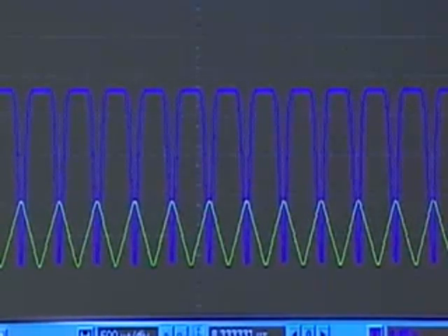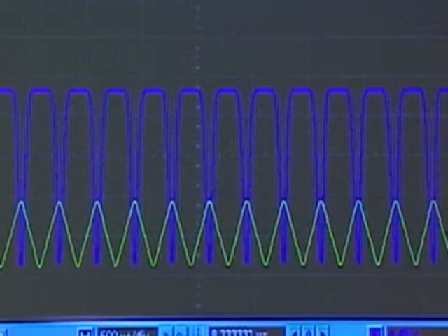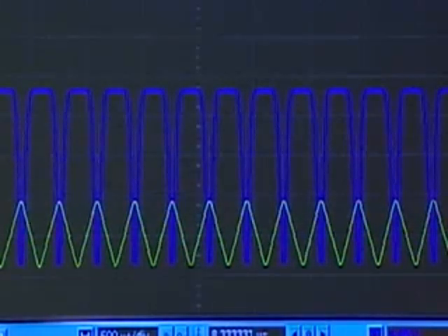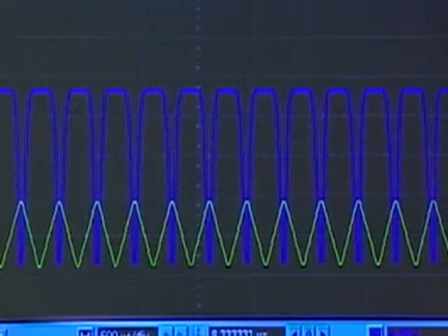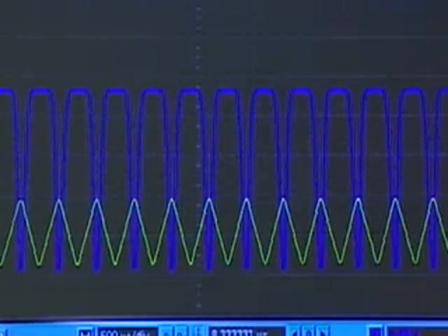Okay. So the triangular wave is my input, and this is my output. This looks nothing like a triangular wave, and the reason is that I don't have the right offset. Okay? So what I'll do is gradually increase the offset on the MOSFET. So at this point, the offset is very low. Okay, I have a very small, near zero offset, and so therefore, my output's a disaster. My MOSFET is not in saturation all the time. So what I'll do here is apply some suitable offset.